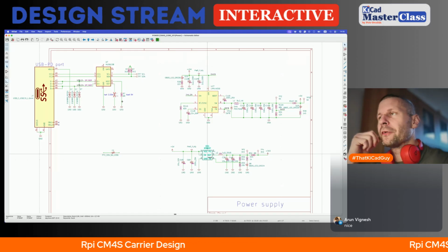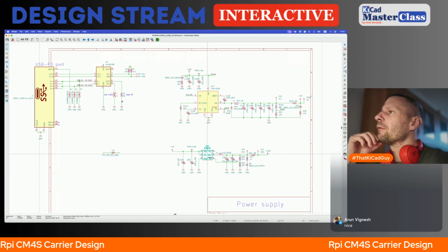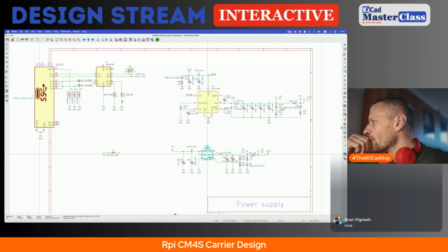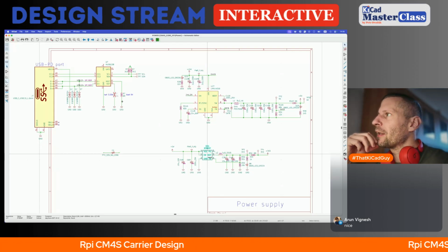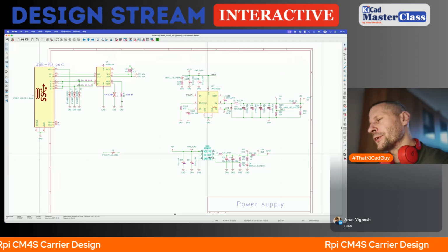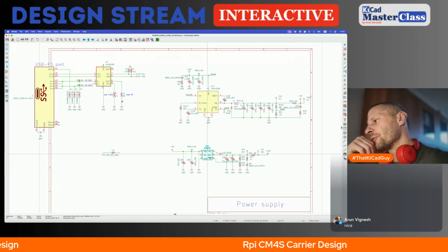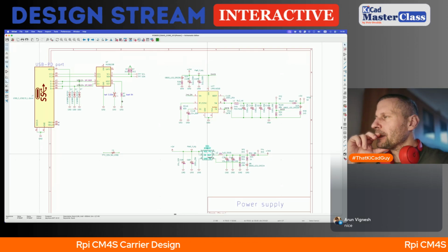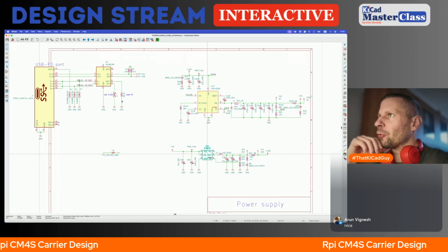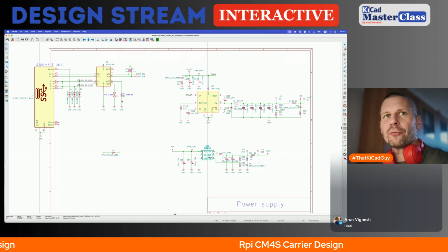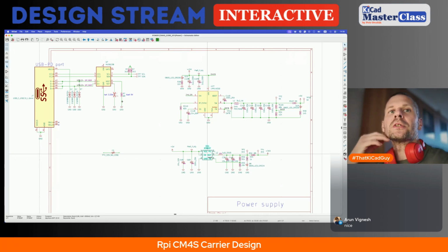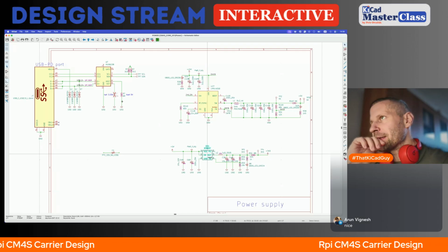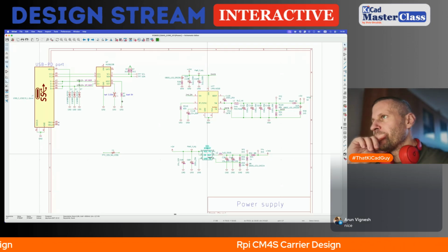Ideally, we need a buck converter with some power path, which means that when the input voltage is the same as the output voltage, the internal MOSFET is constantly on, and we can have the input voltage at the output. It means that the buck converter must allow the maximum duty cycle to be 100%. We can check it.